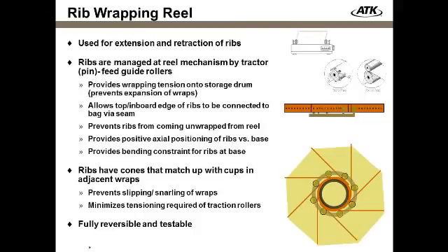So this is a wrapped rib device. Again, we would wrap up these ribs. The wrap would be rolled up upon stowage, then tractor fed out and retained with a lanyard on top, so that as it fed out, it wouldn't just go radially out, but would want to pull up. Then, because of its own strain energy or spring force, it would want to come into more of a basket or a hoop. The concepts for feeding this out include a tractor feed, something that would give positive engagement for both deploying and retracting.